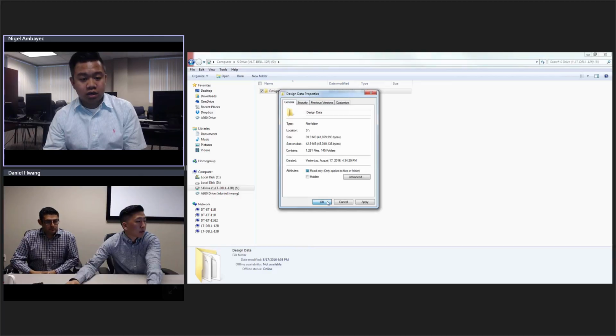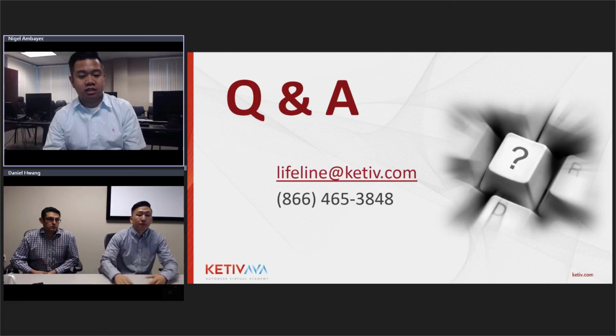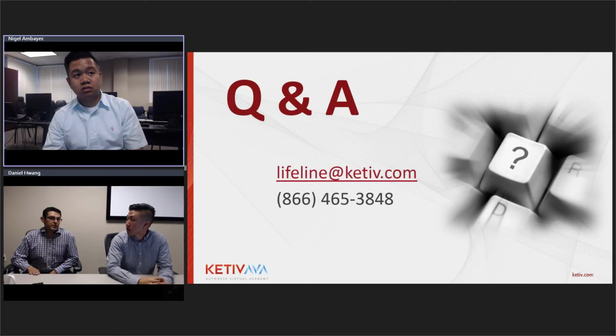All right, and then this came from David. When placing shared design data folder inside the vault, what files/folders need to be checked out? So like you said, the entire design data folder needs to come out of the vault, as well as the project file? There really are very specific files that can be checked out. There's STY.XML files. There's a bunch of them. It's always really hard to tell which one is going to control what. So I like to check out the entire folder.